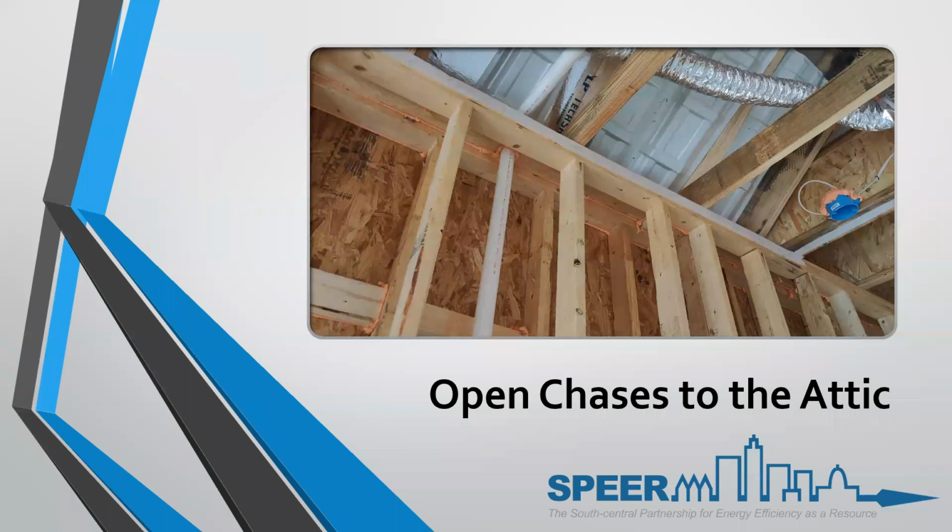Like this, it should have been capped at the top. So closing the gap with blocking and sealing all gaps and seams and sealing around penetrations through the top plate is what's required. As you see, there's a vent stack going through it. It's sealed. It's either a 2x4 or 2x6 that's actually been nailed in place on the top and then poly sealed all the way around.